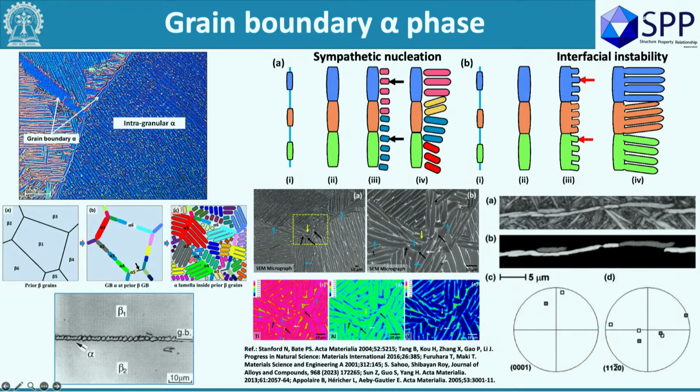If you want to know what that is, please refer to Porter and Easterling, Phase Transformations in Metals and Alloys. Basically this is an alpha phase that forms first in the transformation at the beta grain boundary, just because the grain boundaries are of higher energy and can accommodate the transformation strain much better than anywhere else. That's it.